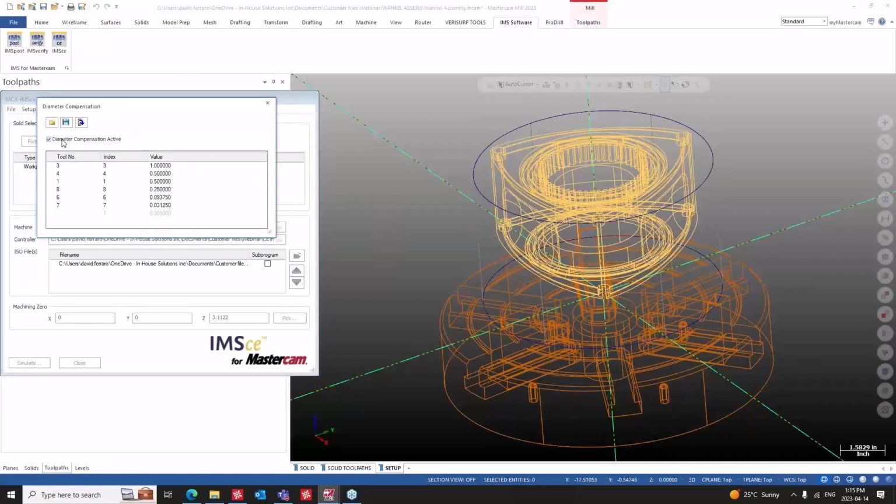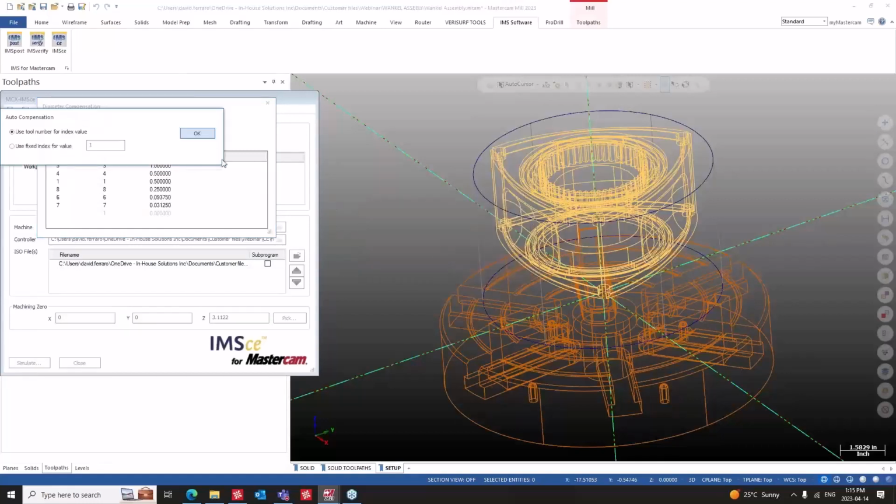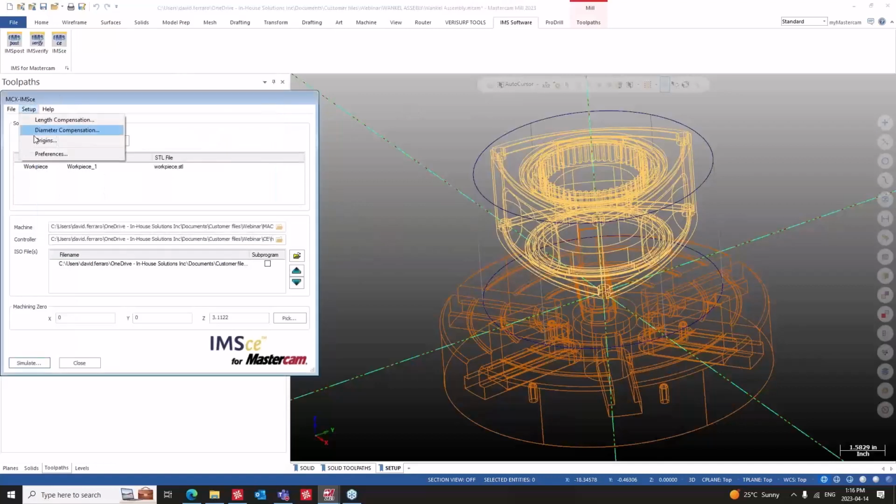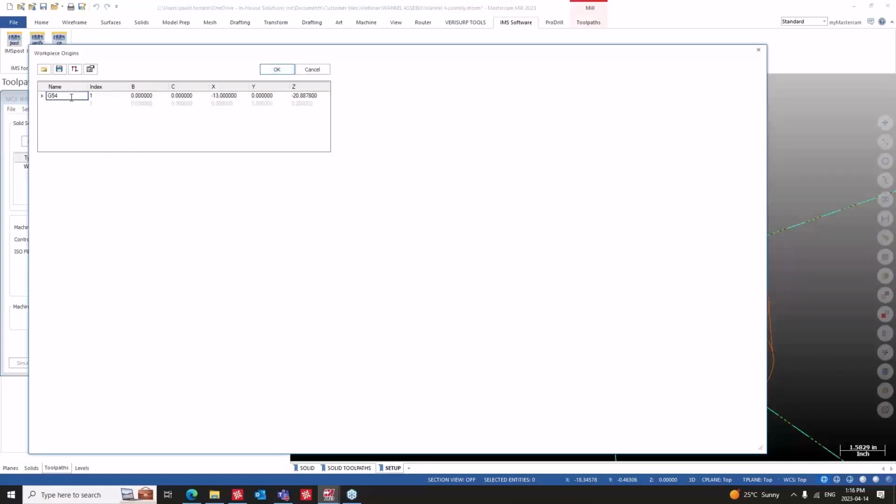Again, for the diameter compensation, we can just click that on, and then we need to call in the table values. Again, from Mastercam, it's calling it in. If we go further with it, now we get into origins. In this program, we're using a G54, so it would literally be typing in G54. If I zero these out and I just make these 0, I just want you to see how easy it actually is. There's defaults here, so we just set the defaults. It's a simple one-click.